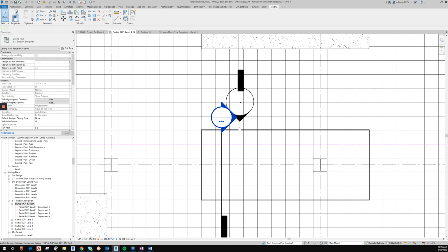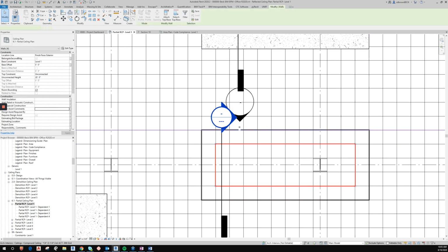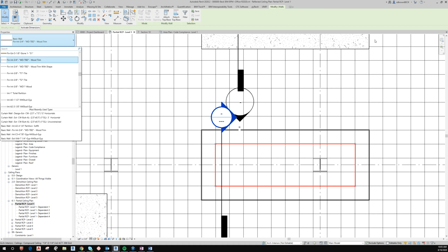So this is going to define the perimeter of our wood ceiling, but we also want the cove. So let's say it's a 2-foot cove. You can use the offset tool, and I set that to 2 foot, and you can put your cursor there and hit tab, and that will jump all those things back and make a copy of them. Right now the heights will adjust those. I'm going to switch these to our A wall type.